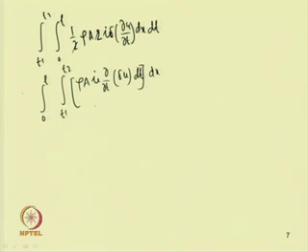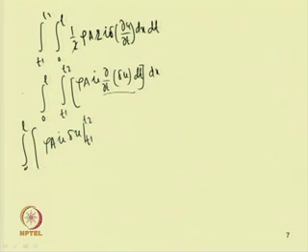To use integration by parts, the first function remains as it is, so rho A u dot. You keep the first function as it is. Now, integrate the second, so the integration of this del by del t of del u becomes del u. This is from T1 to T2. So, one can have 0 to L outside, and so rho A u dot del u.